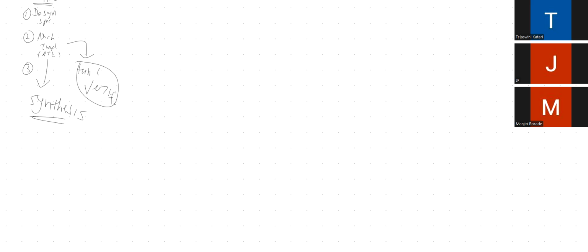Okay. So we are discussing the ASIC design flow and the importance of synthesis. Why do we need to do synthesis? Your answer is that it converts RTL to gate level netlist. So let's say if you directly write the gate level netlist, why do we need to do synthesis? Can we skip that step? No, we cannot skip it.